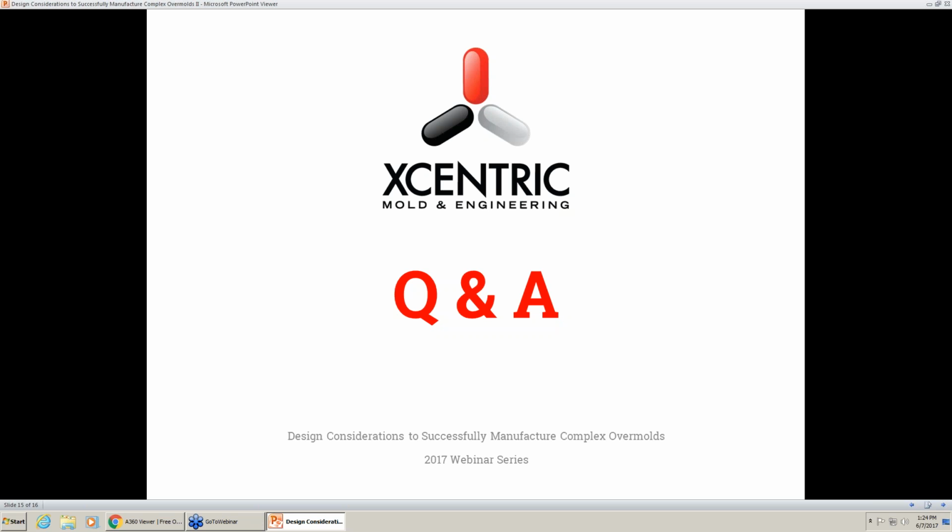Okay. We have another question here, which is for gating, is the core side the most common for gate location? Are there situations where you cannot gate from the core side? That's a good question. And I will say this, when it comes to overmolding, we use a lot of different types of gates. It can all really depend on the type of assembly that we have. And as I mentioned before, a common method that we use is subgating. So we will still come in from the same side of the tool, but we can actually subgate underneath into the opposite side of the tool, into the cavity area, so that we can come back up through the substrate part and gate where you can't be seen on the cosmetic surface. So there's some really tricky ways in which we can try to gate for overmolding. They're not always your most standard methods. So yes, there are ways to gate from the opposite side so that you're not always forcing that gate location onto a show surface, because a lot of the overmolding is for show.